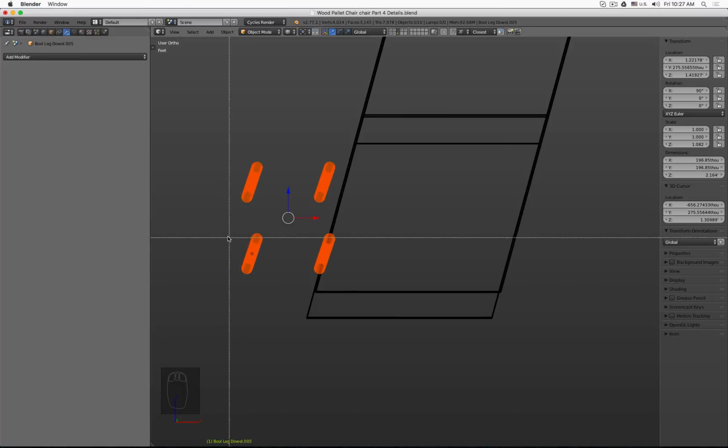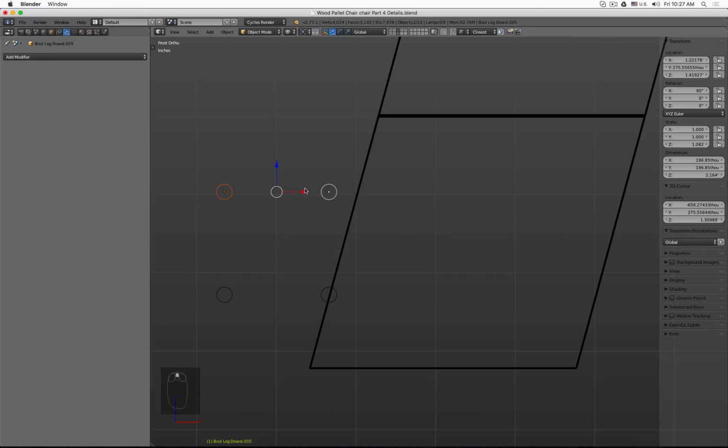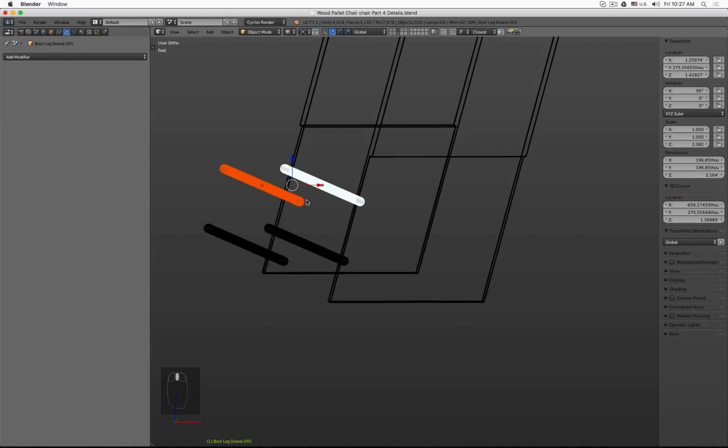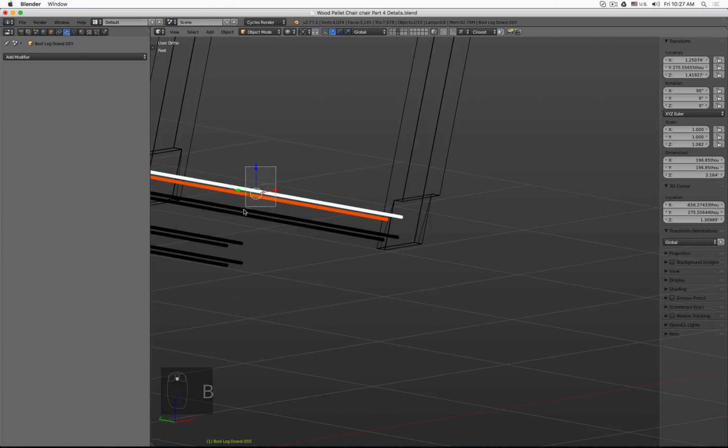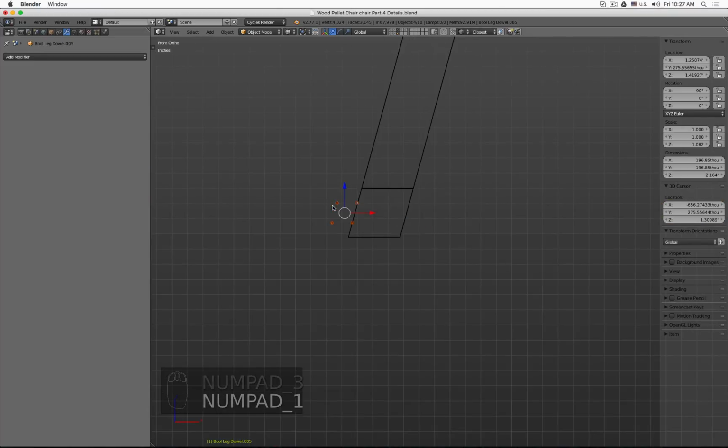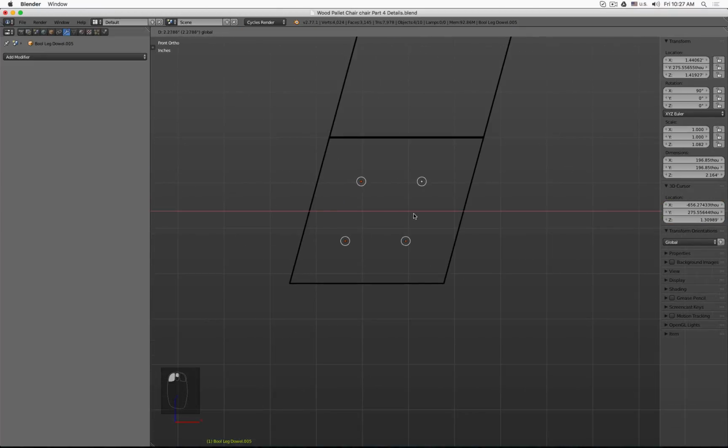Then B, and then with the middle mouse button, we drag over this one to deselect it. So these 2 are only selected. Okay. And then with those 2 at the same time, here I simply slide them over to the right. And now I can select everything there, and then bring it in and try to position it nicely so it's evenly spaced.